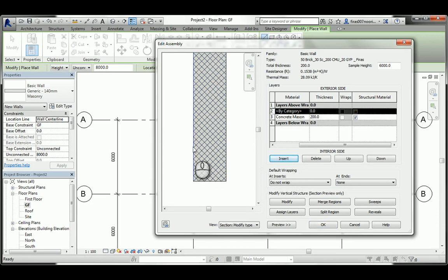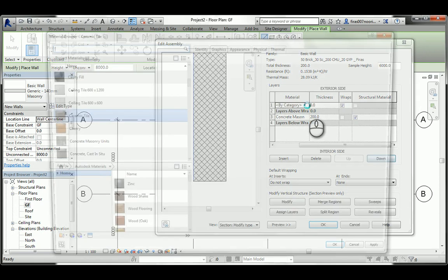Notice that there is an indication here, a blue line shown here. It's inside the core between this one and this one, and we don't want that. I just need to make this separate, and again just hit up. Now see, it's outside the core. That's what we want. That's the right thing, because it's just a separate layer. It isn't gonna carry any weight of the building. So that's the first thing. So what is it? It's not a structure.